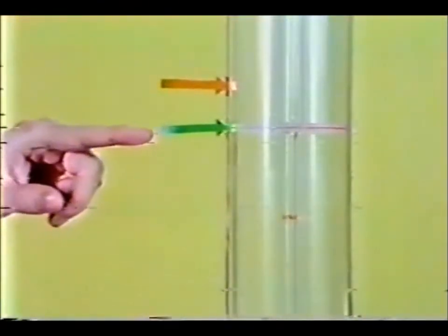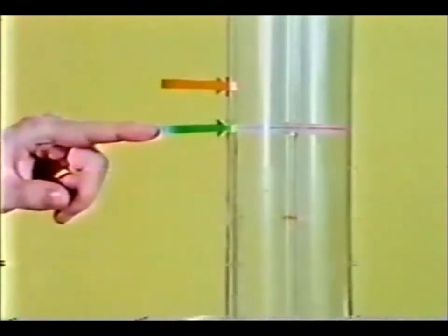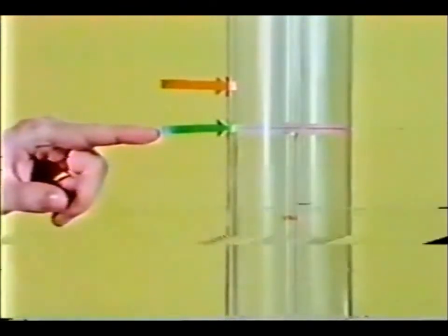When a headwall is added to a concrete or metal pipe, their performance is comparable to that of the thick wall entrance. The headwater pool elevation remains at the same level as for the thick wall pipe. The next improvement is a concrete pipe with a bell end.